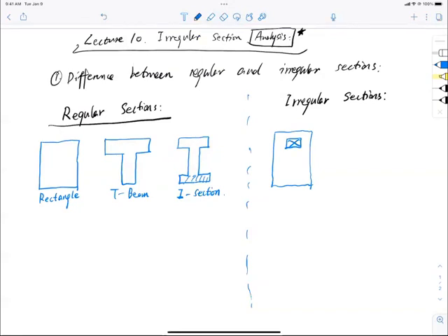So we need to know the capacity of this section, with an opening in the middle of it. Of course, I forgot to put in the reinforcement, right? The reinforcement goes somewhere here for this case, and these are rebars, somewhere here. And also we might have a section like this. So when do we have a section like this? For example, if I have some beams sitting on the shoulder of this beam, right? So I have an irregular section just like that.